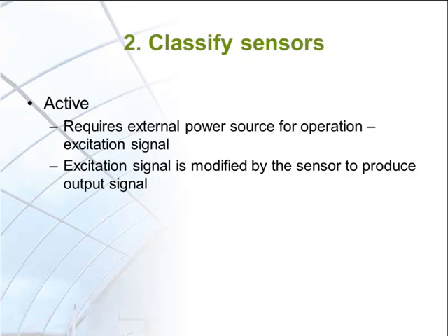It is important to point out that quality of the external power source may have a significant effect on the reliability of the sensor output. The external power source must meet the current and voltage requirements of the sensors. Insufficient electrical current causes voltage drop. An example of this problem is brownout, when light dims due to too many electrical devices running on the same electrical circuit.